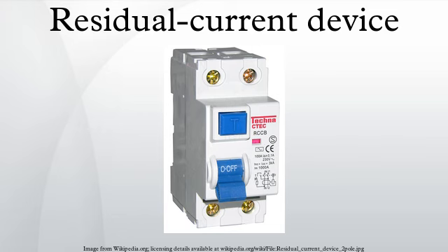Residual current detection cannot provide protection for overload or short-circuit currents, except for the special case of a short circuit from live to ground. For an RCD used with three-phase power, all three live conductors and the neutral must pass through the current transformer. Typical features.